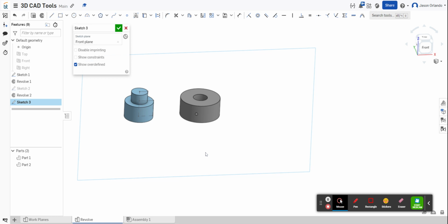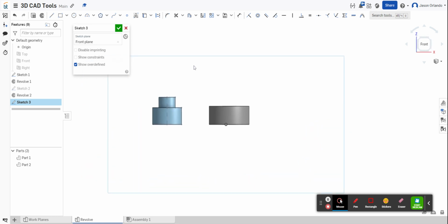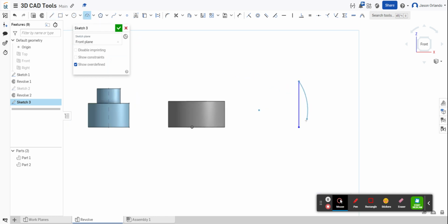What if we wanted to make a perfect sphere? That is a common thing that students sometimes ask. How do I make a sphere? Well, to make a sphere, I'm going to go ahead and make a line first. That line might represent the diameter of my sphere, but I would take a semicircle, exactly half of a circle, which is right here when the center is the midpoint of the two endpoints of the arc.